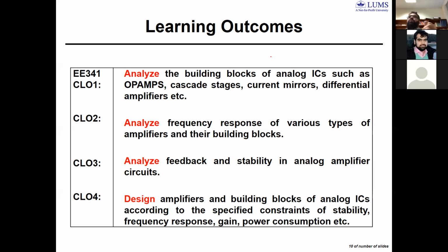A signal is there, and it operates over what frequency range. I can give you an example. When we talk about it, it's like from 20 hertz to 20k hertz. So this means I would like to amplify signals in that band up to 20k hertz. I don't want any other signal to be amplified. Okay? I want only that signal to be amplified, so that it's in the audible range. So my amplifier's bandwidth should be, at this moment, let's say from 20 hertz to 20k hertz. It should be like this. Okay?